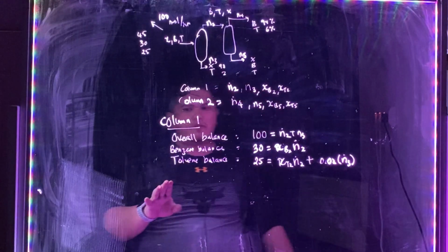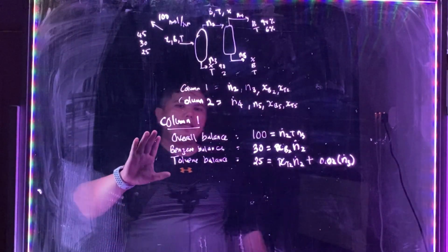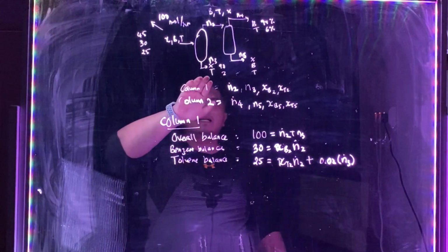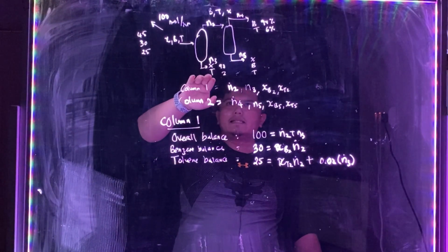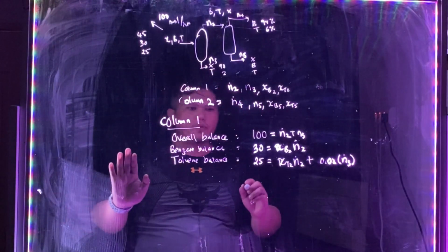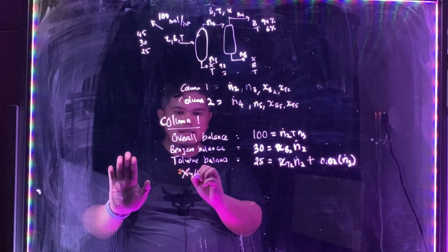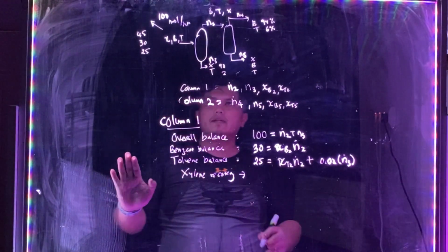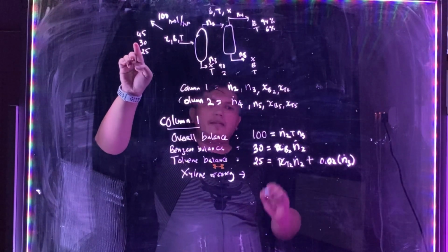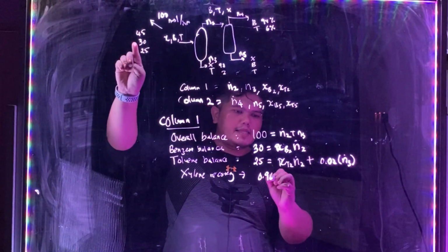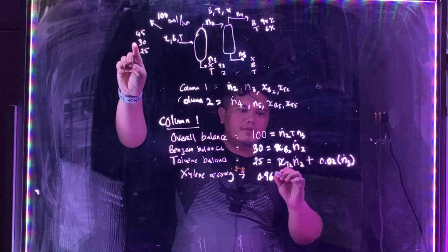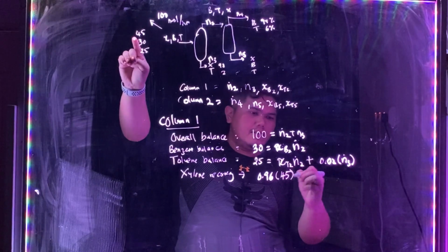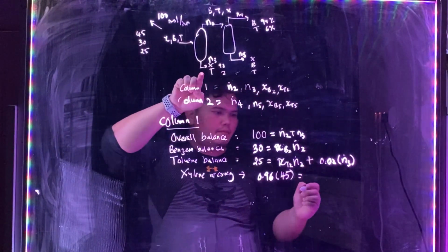We're going to look at the recovery factor later on. The recovery factor is that we were told, in terms of the xylene itself, that 96% is recovered here. So for the xylene recovery, what is the equation involved? We know that 0.96 of xylene, which is out of 45, actually went to the bottom of the column here.